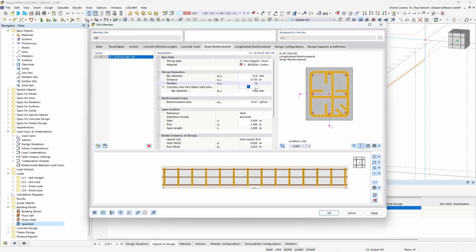And here now, like I said before, if this option was activated, you can graphically activate and deactivate here these shear links. And these stirrups or cross ties will be considered in the shear force design check and also in the detailing design checks. Because we are considering these stirrups or cross ties also in the shear and detailing design checks, we have currently implemented these cross ties for the Eurocode, Eurocode 2, including the national annexes.